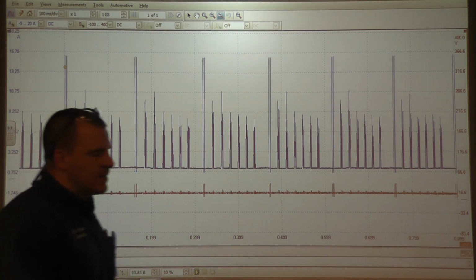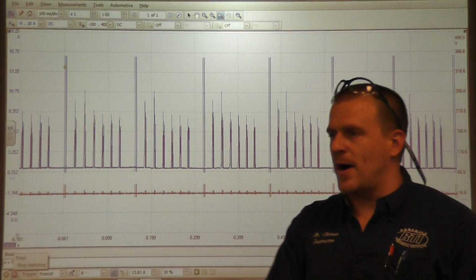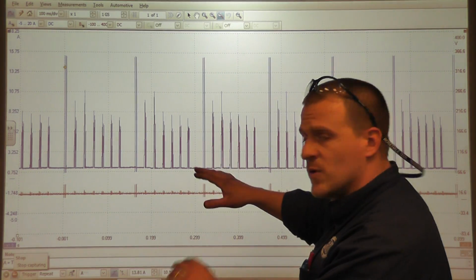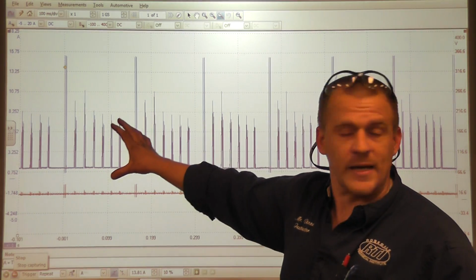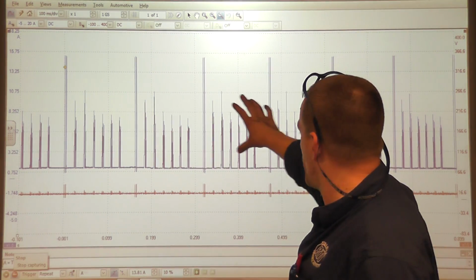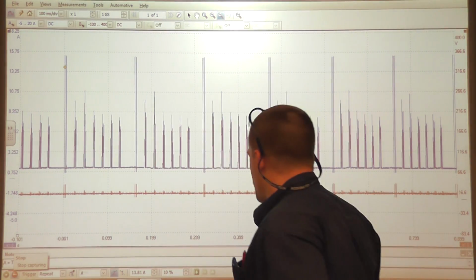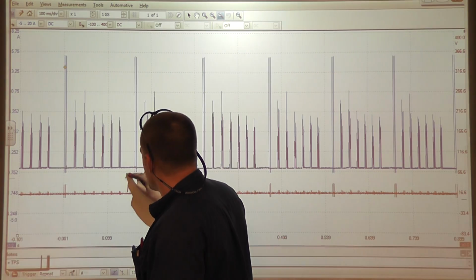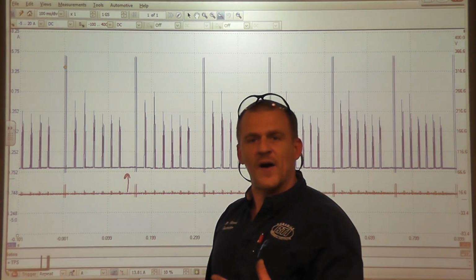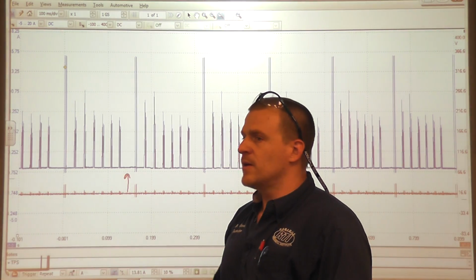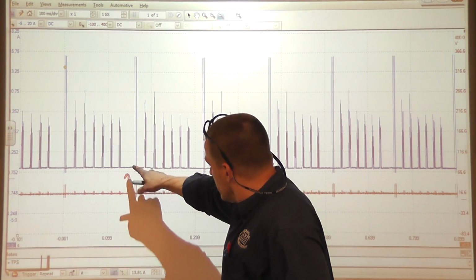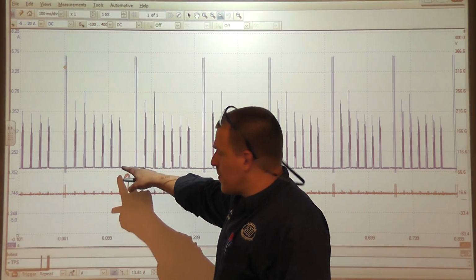Alright, kill it. That's all we needed. So even if it was popping and banging, our main thing, if you look at this picture, if you can see clearly how high the amperage is on this one coil that's on this screen now. Of course, we're still missing one, and the one that's missing is the number 5, because the number 5 is unplugged. That was a good coil, right? Our number 5 is unplugged, and so our missing ramp is actually our number 5.